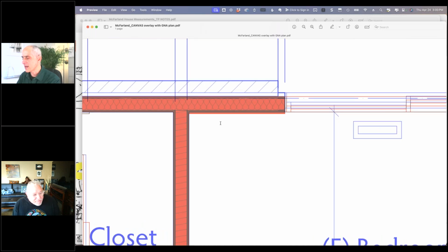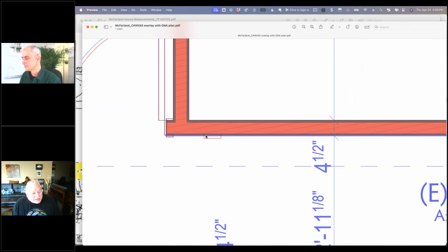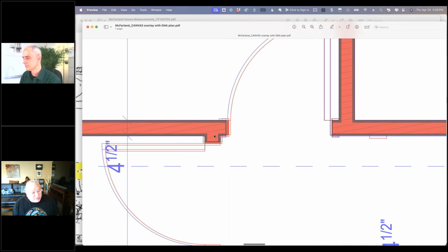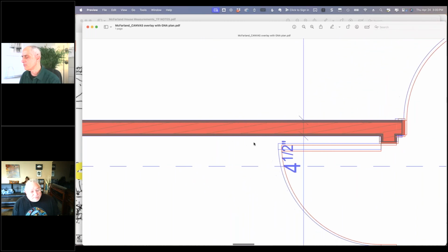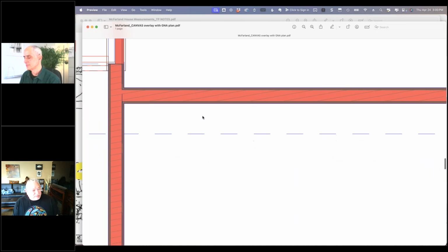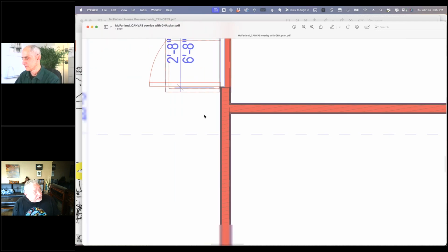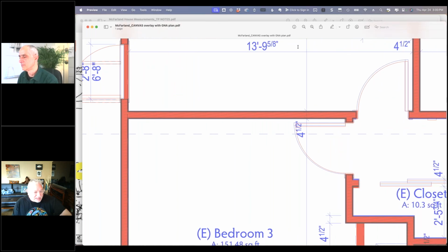Okay, so you were checking accuracy on that. Yeah. You might see some walls that are a little thicker, maybe some segments, a few things like that, but for the most part it's close enough. So you were comparing their model with your manual measurements. That's right, and those blue dimensions are our wall locations, to the outside. I have another type of dimension that goes from the outside face of GWB, and by the way, that's half-inch GWB, so we're comparing apples to apples here.